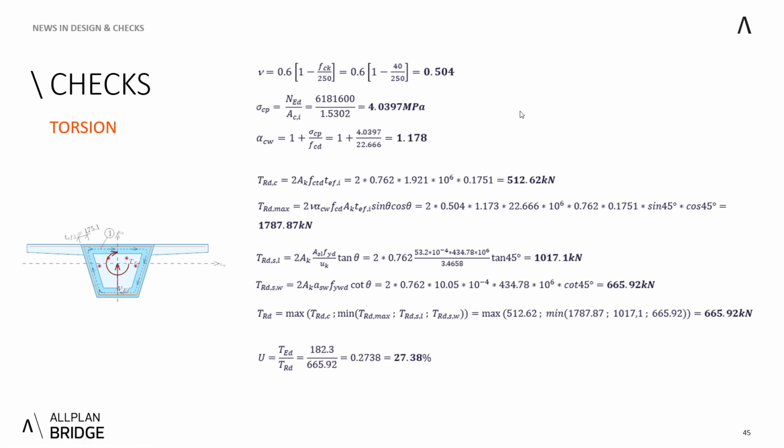I've covered some of those things already in the shear, those first three equations. So we can then form these equations of the torsional resistance purely of concrete, then of the concrete diagonal strut. And then we have two things for the torsional resistance for the rebars.